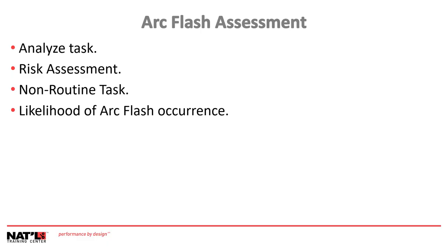If the likelihood of occurrence of an arc flash hazard exists for either routine or non-routine tasks, employees shall use appropriate safeguards that shall include one or a combination of the following means. Insulation shall be suitable for the specific conditions, and its components shall be permitted to include glass, porcelain, epoxy coating, rubber, fiberglass, and plastic. When dry, such materials as concrete, tile, brick, wood. Insulation shall be permitted to be applied to energized or grounded surfaces.